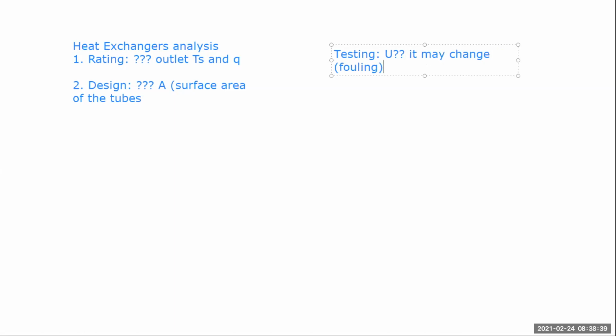When fouling is there, fouling usually is a function of time. As the time passes, the fouling factor increases. And actually there are models that talk about how the fouling factor increases with time. Some models are saying it is increasing linearly with the number of months. Others would say, no, it is increasing asymptotically.